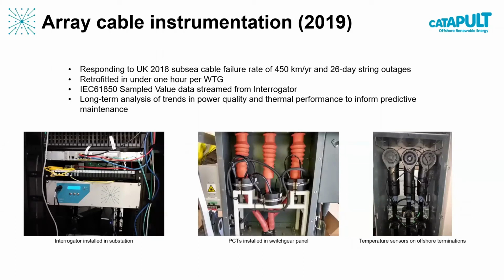Or you're working in a system where, even if there's a fault in the middle of the string, we can see past that fault and still take active measurements. It's like being able to operate beyond the horizon of a fault, because we're not requiring the power supply to keep the information coming into the merger.